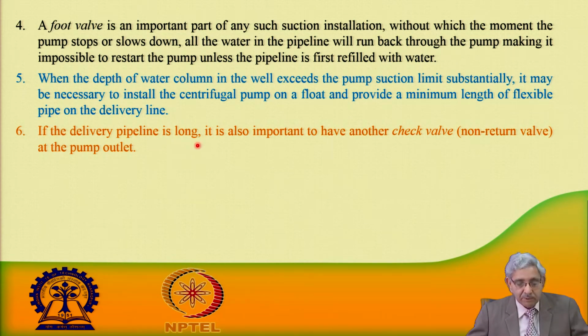If the delivery pipeline is long, it is also important to have another check valve or non-return valve at the pump outlet.